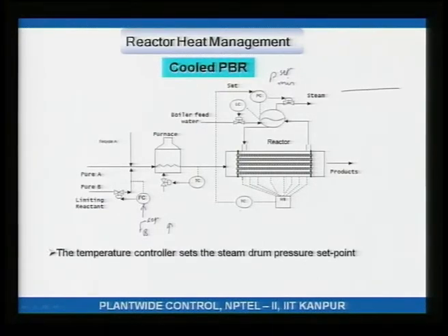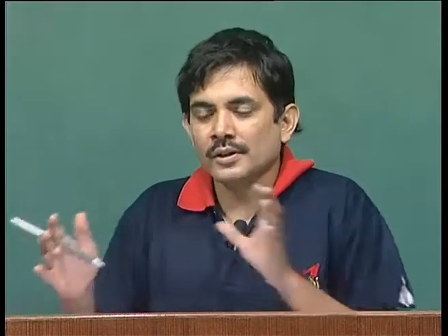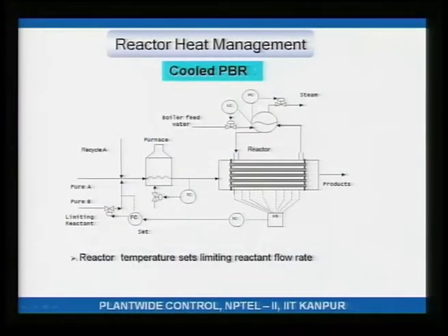Now, because the temperature can vary due to local disturbances, to make sure that my hotspot temperature is controlled for local disturbances, and because P set is manipulated, it will have some variability. Okay. So, on average I will have to operate slightly above P set min to ensure that temperature can be controlled for local disturbances that occur in the reactor. On the other hand, here, this is set at P set min. So, there is no back off, I am operating at the lowest possible pressure at all times.